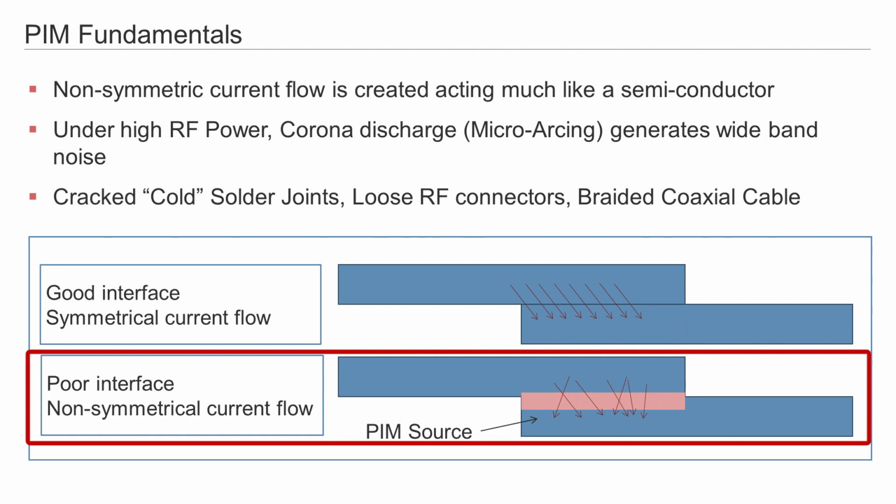Another example is at the assembling of a feeder connector. If the cable is not prepared in the correct way, and parts of the dielectric are clamped between the cable's outer contact and the connector's outer contact, this will result in PIM too.